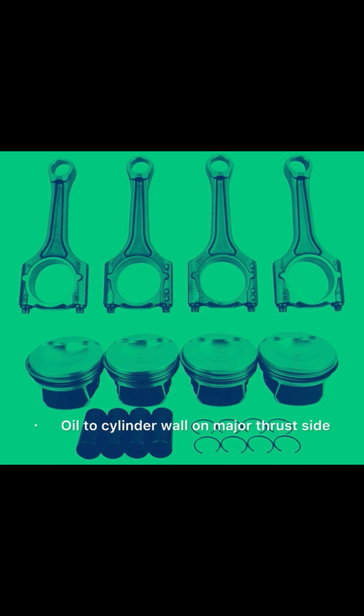18. How are pressed piston pins removed from the connecting rod? Need a special holder. Use a press. 19. How are pistons cleaned? Pressure washer, light plastic brush, solvent tank, clean grooves with ring scraper or a piece of an old ring.